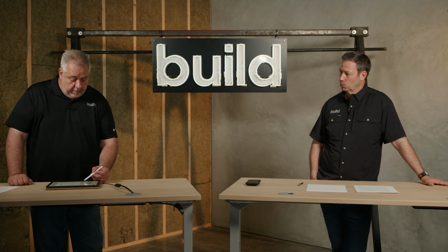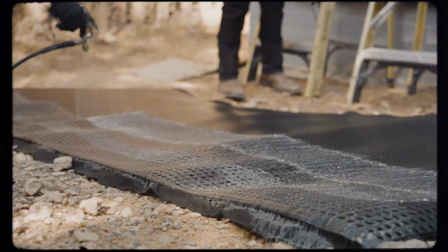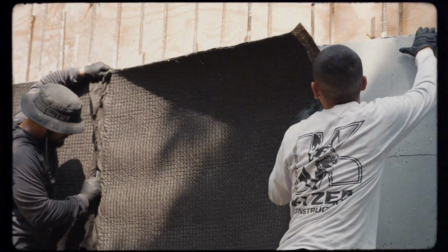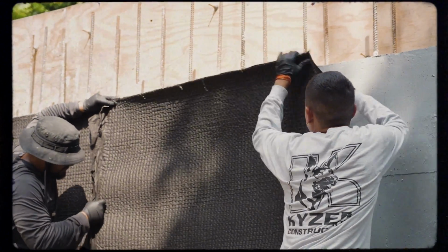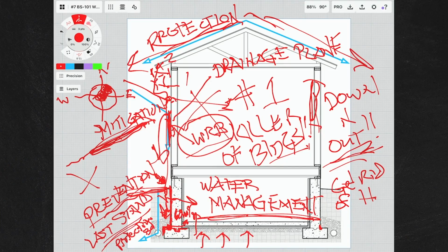So the 60 mil, but what you want to do here is put some type of protection board or drainage measure. Yeah, I'd add the word drainage on there too: a drainage and protection board. So that when you do backfill, you notice on his diagram, he's got crushed rock down there at the footing drain, and there's usually a filter fabric over top of that crushed rock.